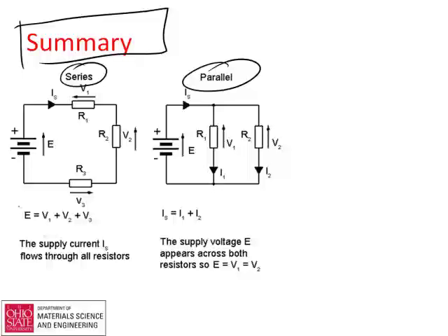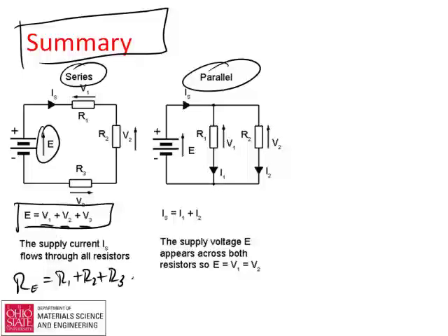And the big thing is that the total potential that you put on the circuit has to be the sum of the potential drops across each of the resistors if you have things in series, and then R for the equivalent circuit is R1 plus R2 plus R3, etc. And then if you have things in parallel, you've got the same potential that runs across all of these, you have the same voltage drop across each, and then the total current would be the sum of the currents that go through each of these guys. Okay, so that's parallel, and we'll come back to this in sort of an abstract way when we get to wires in a minute.